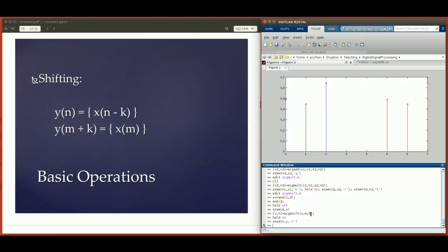And if you put a positive number as the input, as the shift amount, then the entire signal is going to be shifted to the right. So it's going to basically delay. If you consider the horizontal axis to be time, then a positive amount of shift is going to delay the input signal by the amount that you entered as input, 5, for example here.